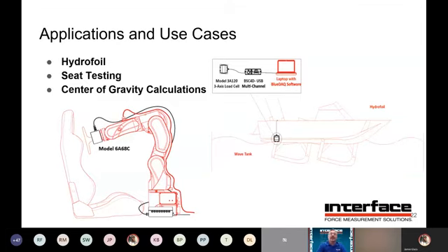Wasn't what you expected. So then the next test, maybe with a different seat back, the hinge lasts longer, but it's really because you were applying less of a lever arm and you didn't realize it because the foam, say, wore more quickly or the shape was slightly different. So very interesting to measure. And then, once you know what's going on, you can either redesign the test such that it, say, minimizes bending, or try to make sure that the characteristics are the same when you run a different specimen, for apples to apples comparisons.